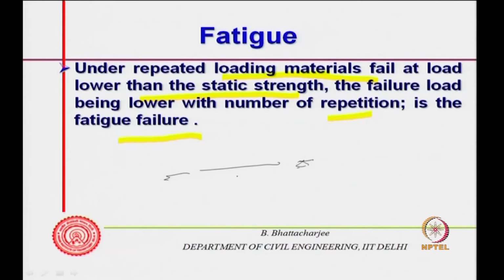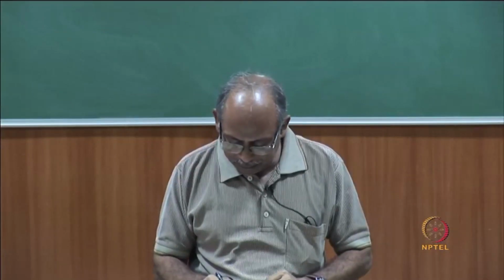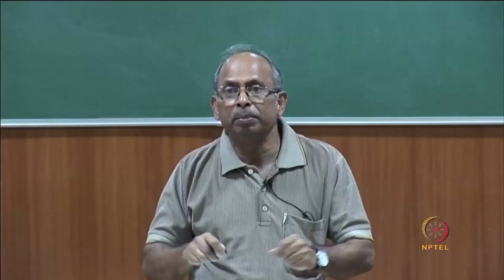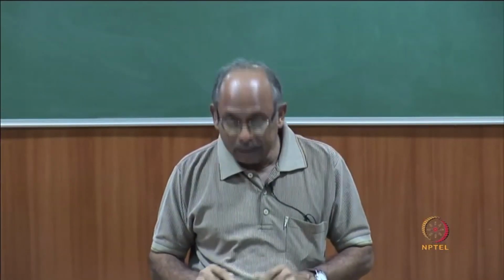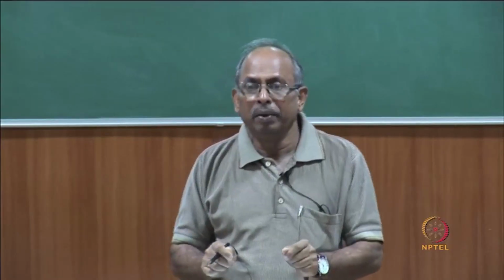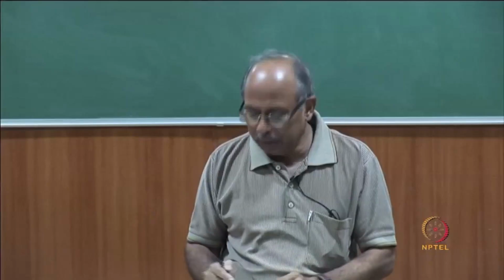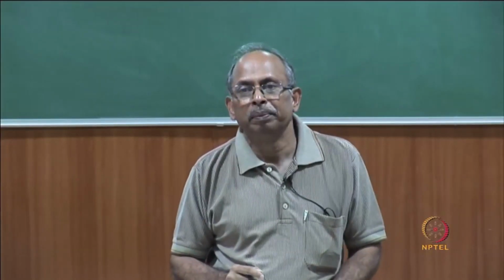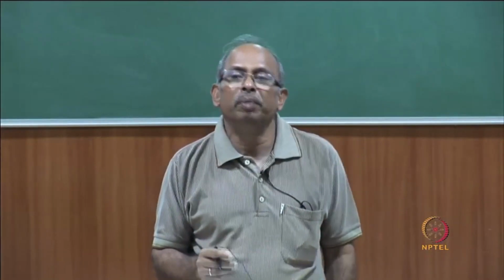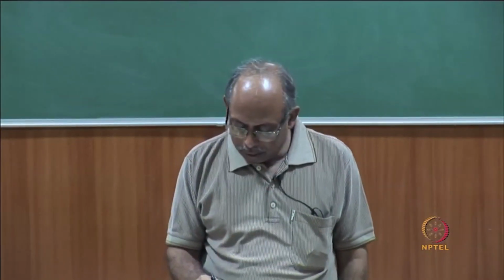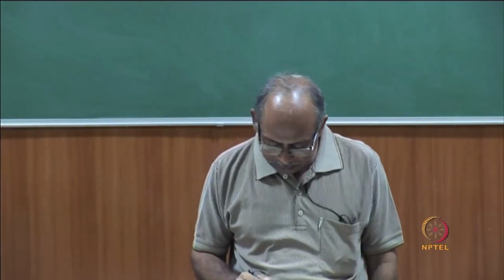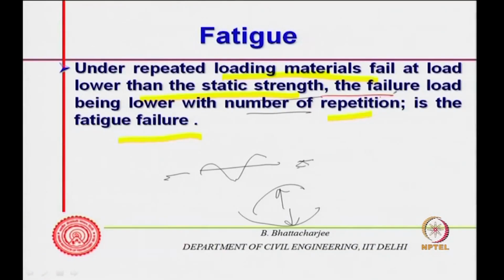But if I try to bend it in this manner, it reverses the stress. There is a reversal of stresses. So, first you bend it in this manner, then bend in the reverse direction. You go on doing this, and after some time it will break. So, with repeated loading it fails at a much lower load, and that is basically a fatigue failure.